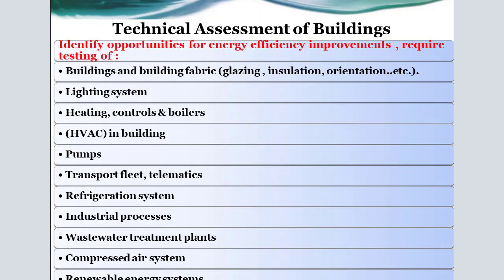Now we have another issue about technical assessment of buildings. What we must do while we are visiting a building in the energy audit process. Here it's important to identify the opportunities for energy efficiency improvement, and this requires testing of the building and building fabrics such as glazing, insulation, orientation, and so on.